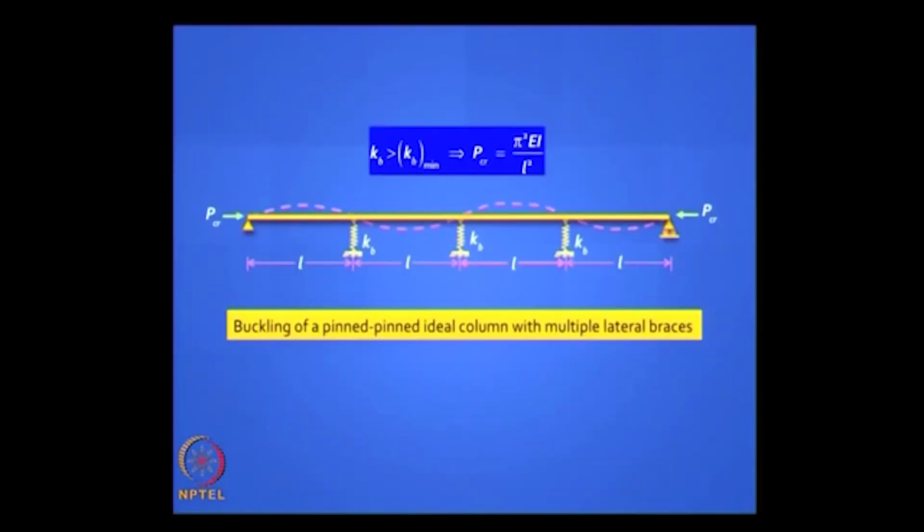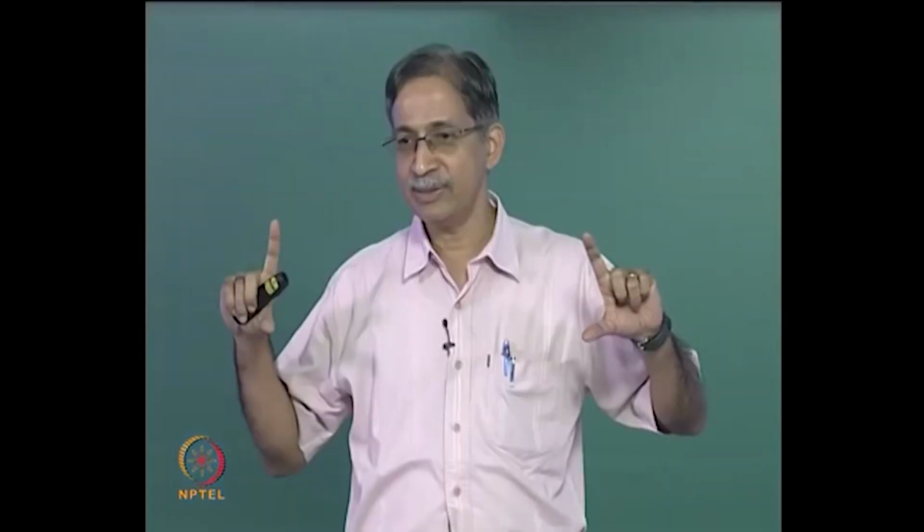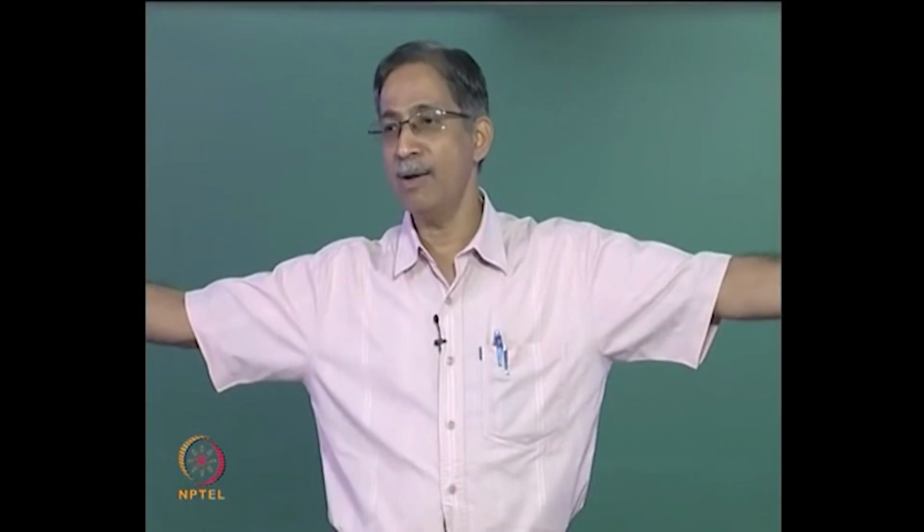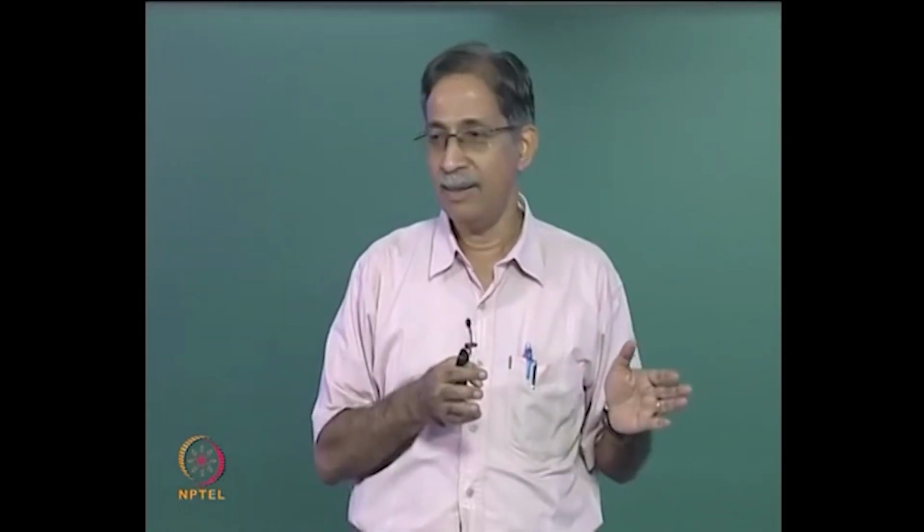So for practicing engineers, these kinds of fundamentals are very important, and it is especially important when you have a very long column. You can work out the minimum bracing needed. It need not be infinite, but you have to provide appropriate stiffness to make a long column behave like a relatively short column to increase its capacity.